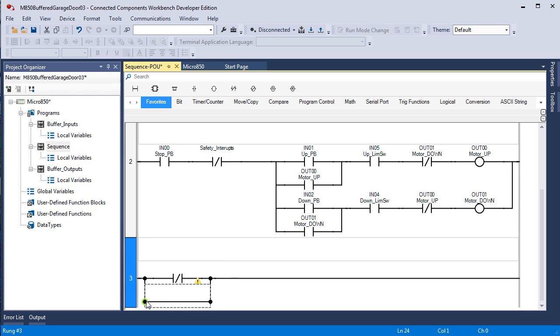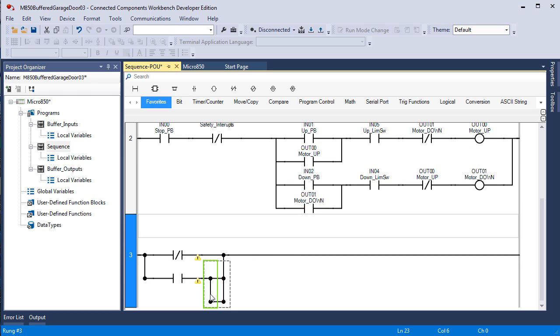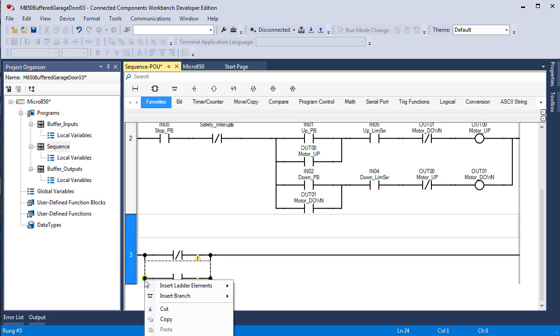I'm going to put the focus here, and a single click there puts in a true if on. If I have the focus here and I click here, that isn't what I want. So I'm going to click on this and delete it. Instead, I'm going to click here and insert branch below. Actually, this is a slight improvement over RSLogix, because with RSLogix, it would allow you to add a branch that goes around an instruction that is not extended down. Even though logically it's extended down, it would allow you to put it in there so you had a next branch and a branch start instead of just a next branch. We have 1, 2, 3, 4, 5 branches.